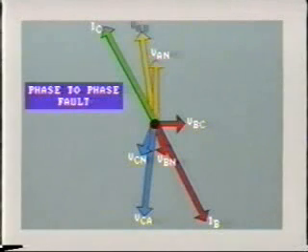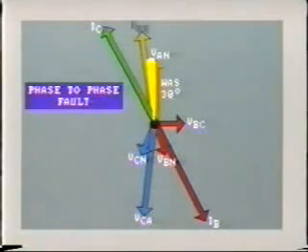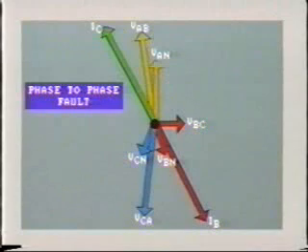This causes a change in the phase relationship of VAB, which is the voltage between the lines A and B. As we know, this is the difference between VAN and VBN. Subtracting these phasors, we find that VAB moves back in phase angle. It now leads VAN by less than 30 degrees. The magnitude of VAB is also reduced slightly. We can see that this phase-to-phase fault has seriously distorted our previously balanced condition. Now let's look at the line currents.